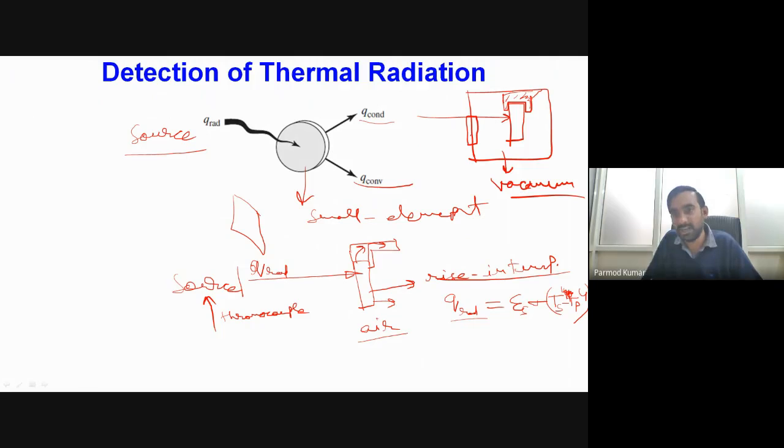Okay, so the material of this enclosure, at any particular location, should be such that it allows optical access. Generally, in the case of thermal radiation, the spectrum of wavelength is 0.1 to 100 micrometers. In this we have some visible light, a small portion of ultraviolet, but the majority is infrared radiation, IR radiation.